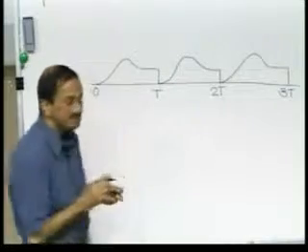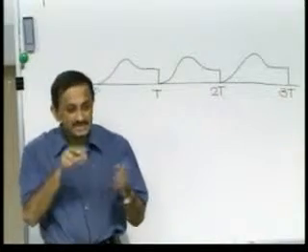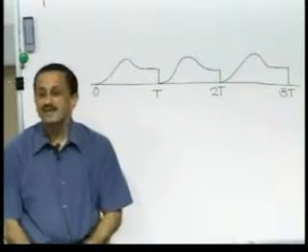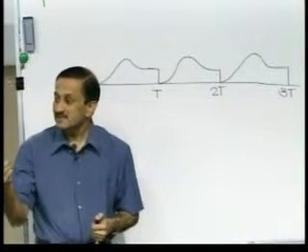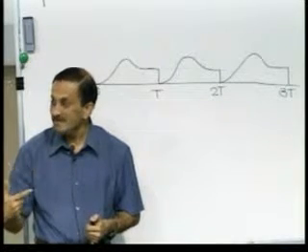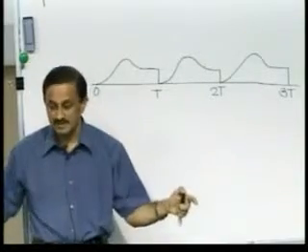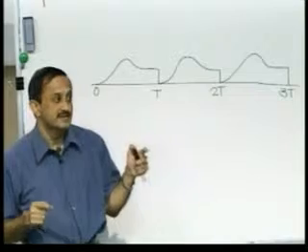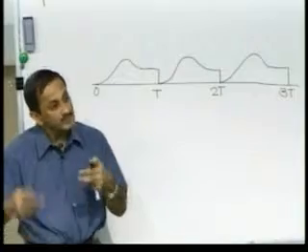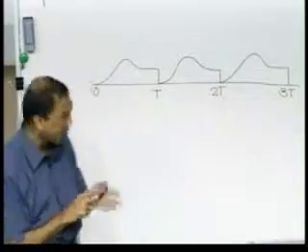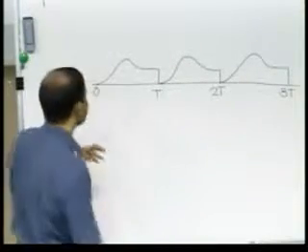Let us assume that we have an oscilloscope which can sample the waveform and interpolate between samples. We have already been exposed to the idea of interpolation, haven't we? We discussed that the method of reconstruction of the waveform from its samples is essentially a method of interpolation. We use the sin x by x pattern to interpolate. And of course, we shall also discuss later that although the sin x by x pattern is an idealistic pattern, one might use simpler patterns at the expense of accuracy, right?